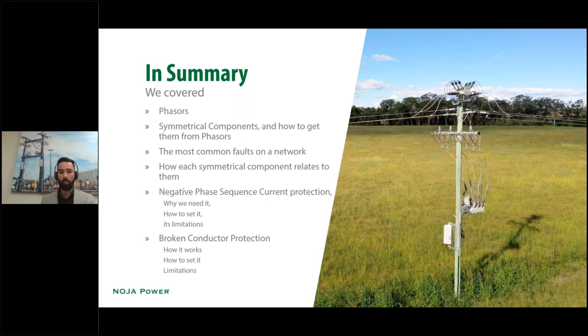Now, today, if you are using our OSM reclosers, the firmware is free to upgrade to beyond 1.16 to be able to gain access to this. And I think that there can be some really good safety benefits by being able to detect these scenarios, because I've heard of too many cases of broken conductors floating in the air that go undetected until there is some serious damage done. So it is important to have a technique to be able to address this.